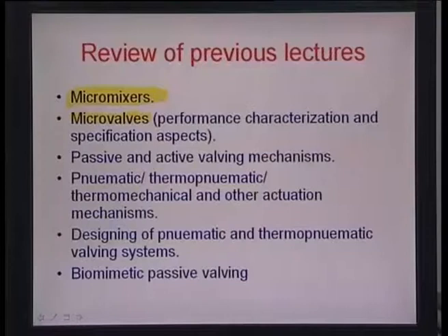We then detailed micro valves, essentially studying some basics about their actuation mechanisms, their performance characterization and also specifications. Some of the aspects like valve capacity, the leakage ratio, the power requirements, and other aspects like material selection and biocompatibility were discussed for designing micro valves or micro valving systems.